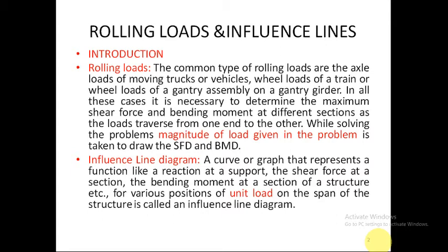How the loads get transmitted from one end of the girder to the other end is taken into consideration here. We also will discuss how to determine the shear force and bending moment at different sections as the load traverses from one end to the other end. While solving the problems, the magnitude of load given in the problem is taken to draw the shear force diagram and bending moment diagram. On the contrary, in influence line diagrams the load will be taken as a unit load. That means 1 kilonewton will be considered.